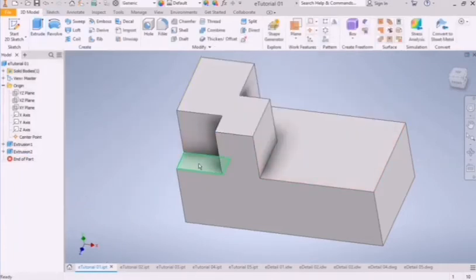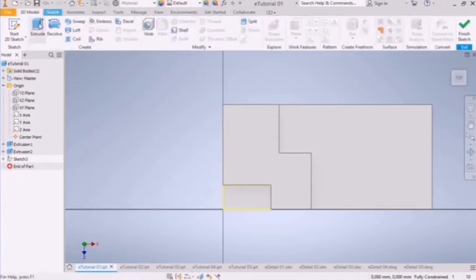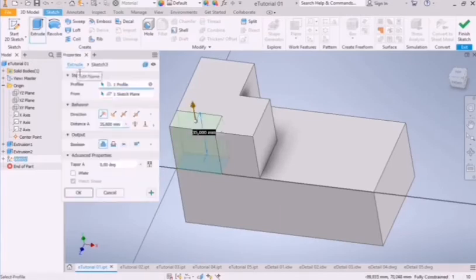Okay, and then now we click on here, and then we select sketch. We wanna cut the entire part. Okay, let's project geometry. Yes, we're happy. Our geometry has been projected there, so that the area is highlighted in order for us to cut.